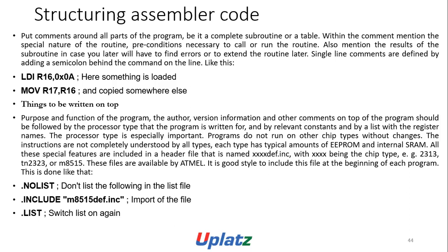All these special features are included in the header file that is named xxxxdef.inc, where xxxx is the chip type, like 2313, 2323, M8515. These files are available from ATMEL. It is good practice to include this file at the beginning of each program.